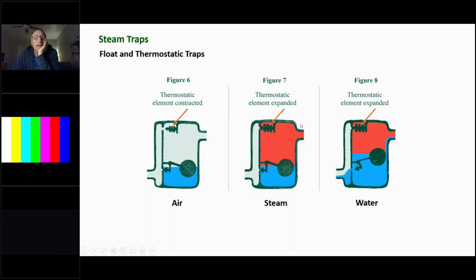And then if it fails, the steam gets to the pump on that boiler feed unit, which the pump usually has a seal in it that's rated for 225 degrees. And if you start injecting live steam into that boiler feed tank, it will probably start rocking and rolling, and it will burn that seal up. You'll have a leak, and you'll have to go back and repair that pump now, which is never a fun thing to do because you generally have to drain the system to do that.